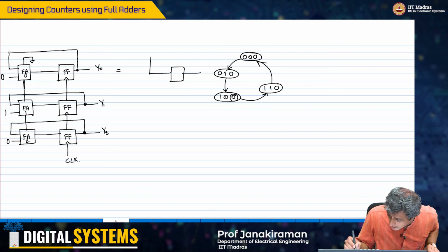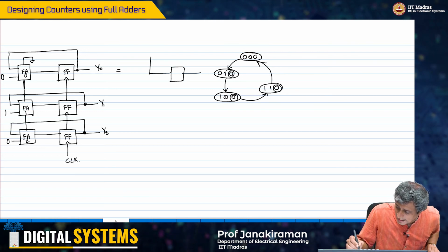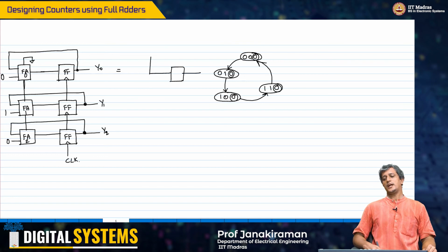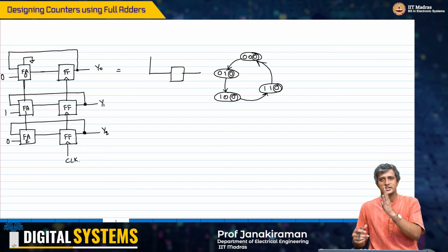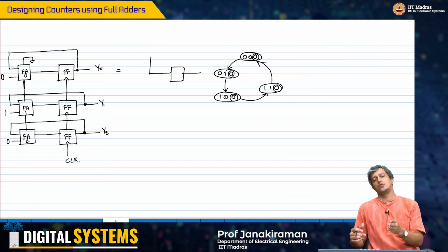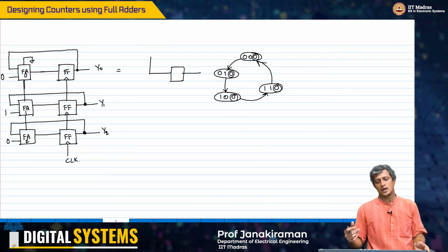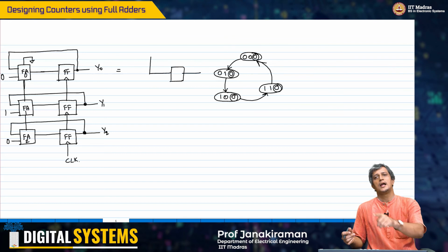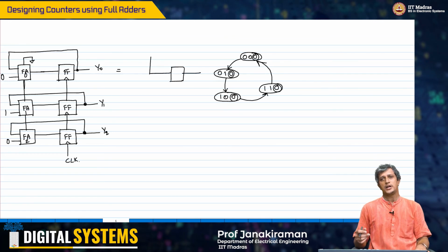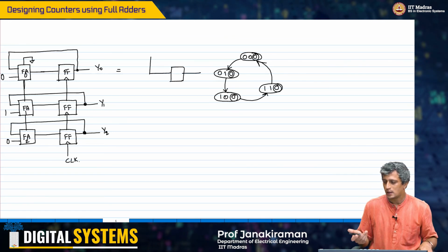You see that this state actually is just a 0, right? You have nothing to do here. The output of that Y0 is simply 0. You don't have to do anything or change that state. So all you have to do effectively is to do 2-bit counting and fix that other bit to 0, right?